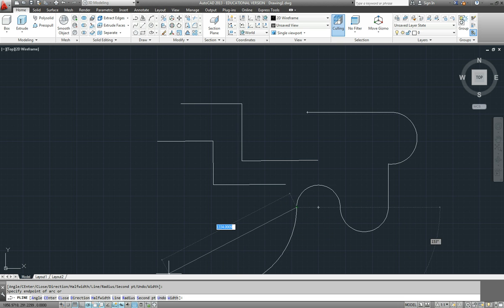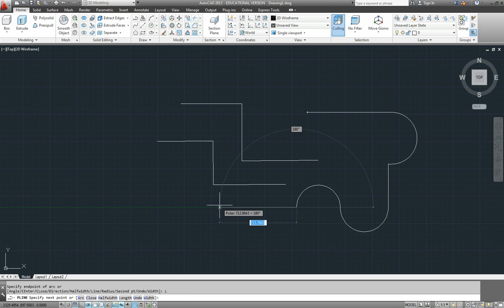Now the other interesting thing about polylines, and one of the main things we use it for in 2D drawing, is that we can change the width of the line. As it stands, it's described as having a width of 0, even though you can see it. So to change the width, we can go to W and it asks us for a starting width and a finishing width.